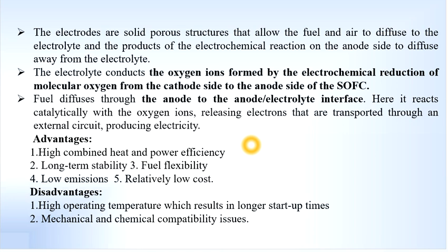As I said, the electrodes are of solid type and they are porous structures which allow the fuel and air to diffuse to the electrolyte, and the products of the electrochemical reaction on the anode side to be diffused away from the electrolyte.